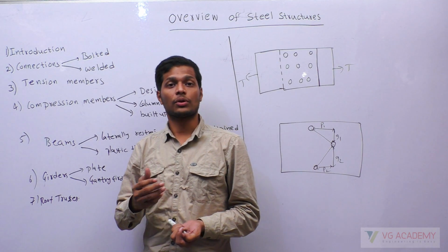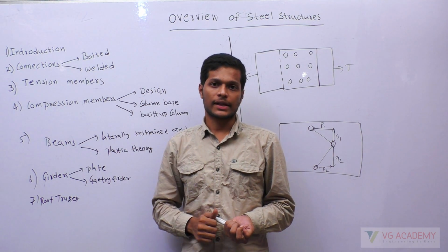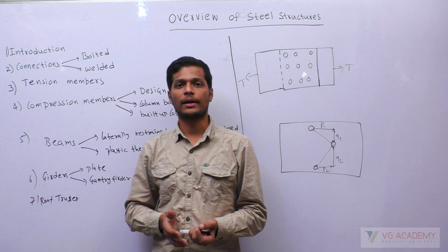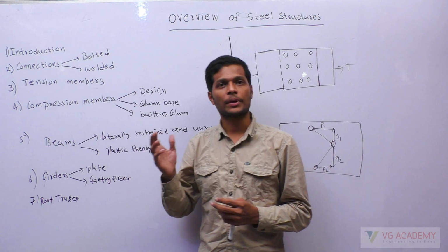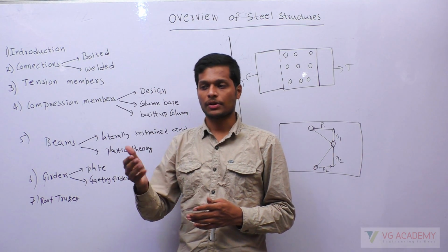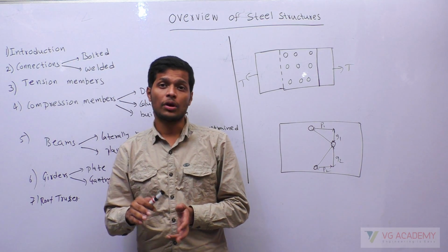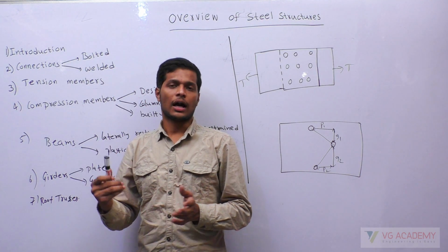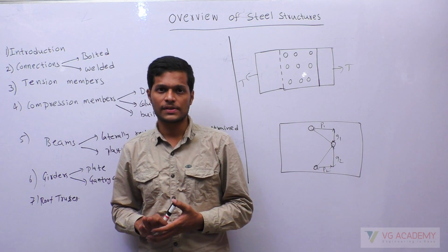Apart from that, we know that unlike concrete, steel cannot be prepared on the site. Steel will be prepared as a rolled section, hot rolled section. So we have a separate steel table code, for the list of sections that are available. In concrete, we design a cross section and place the formwork, steel, and do concreting according to our design.